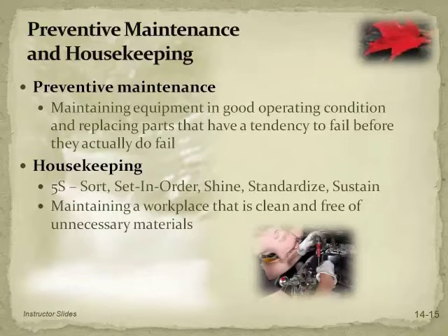So we need to do periodic inspection of that fan belt, and when we see it starting to wear and start to have cracks in it that are indicators that it may fail in the future, don't wait until it breaks and then the machine can't be used. Go ahead and change it before it actually breaks.